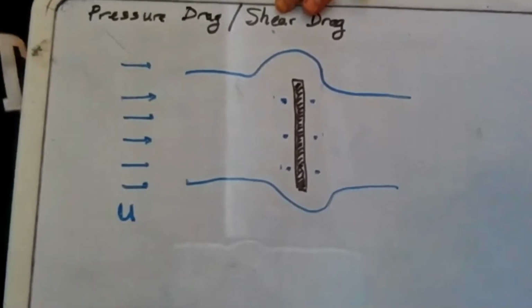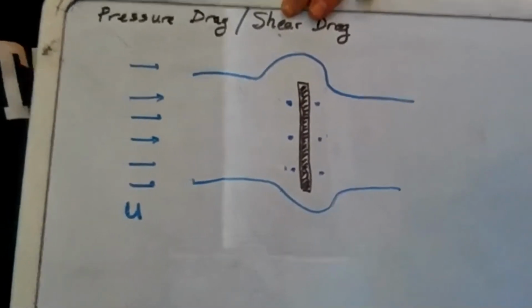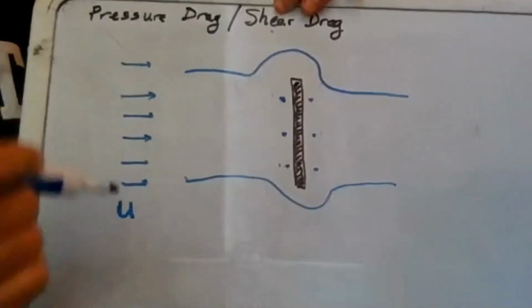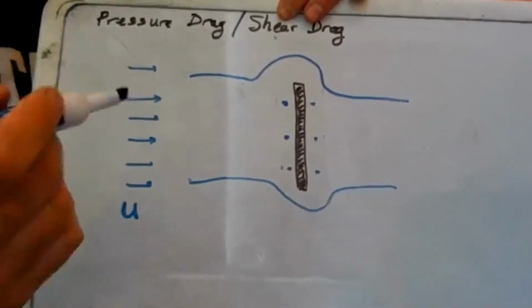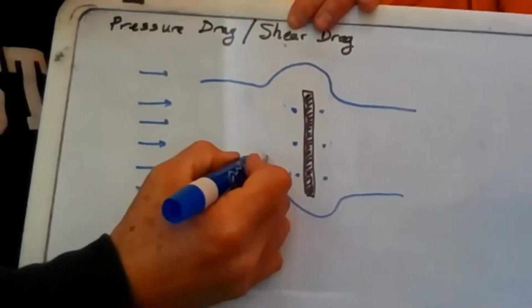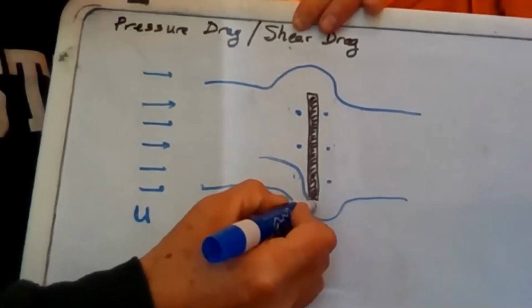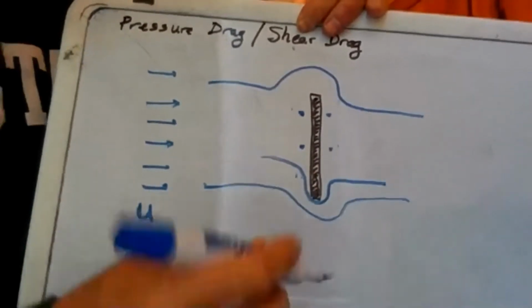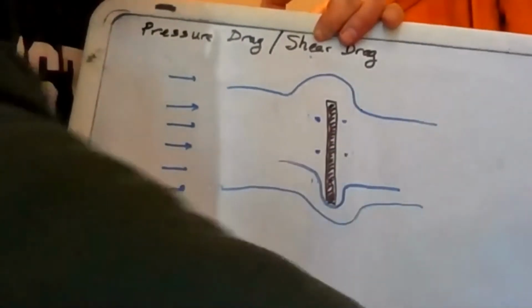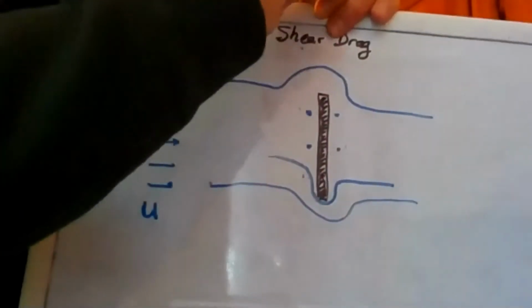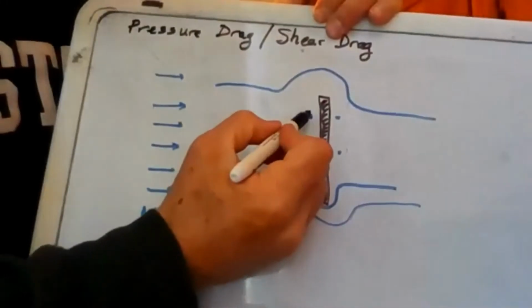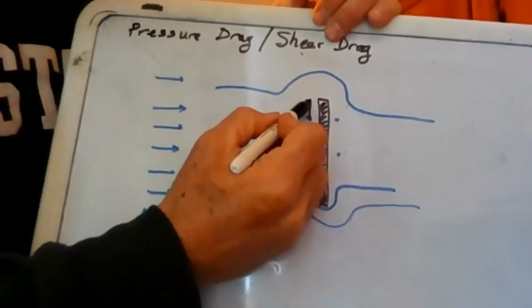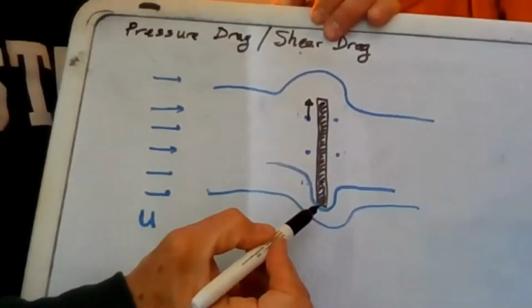where we actually get the streamlines. We had streamline functions, we had velocity potential functions, and you can do this for low Reynolds number cases, or for some cases actually, where we can get a streamline that goes here like this and then comes around there like that. Okay, in short, if you get really close to the plate, the fluid is actually going to be moving vertically here like this at that point there.